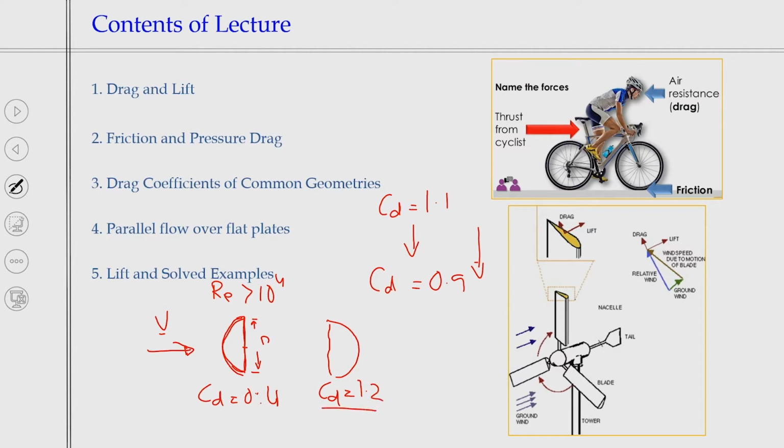That means the drag force exerted when your umbrella is parallel to the velocity will be 0.4 times half rho v square into A, the dynamic pressure times A. But if I hold the same umbrella differently, the force because of this orientation will be 3 times the FD force.